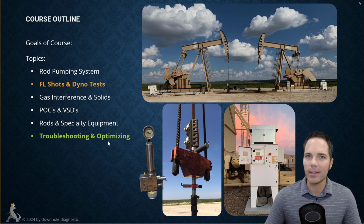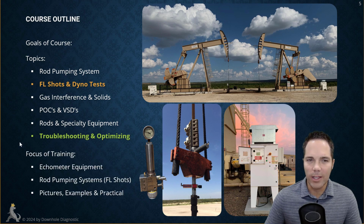Also optimizing. Once we get data from the well, what is the best way to run this well? A lot of times optimization is quite clear. If you have gas interference, what is optimization? Well, that means improving your downhole gas separation design to try and remove that gas interference. But we will focus on this all throughout the course.